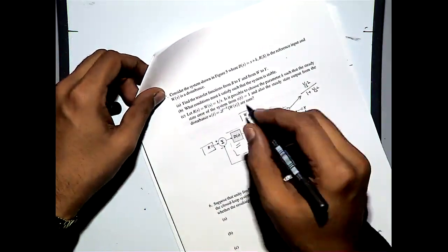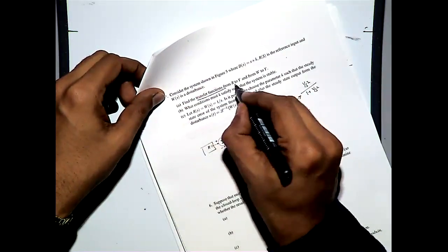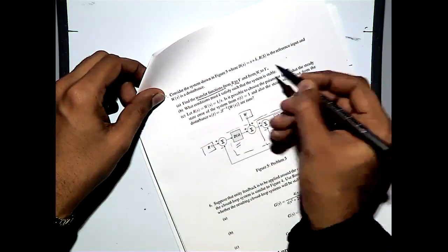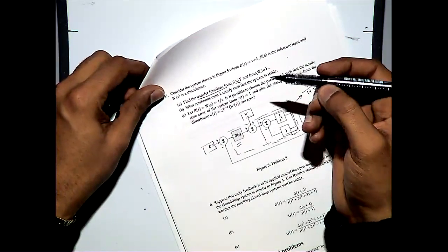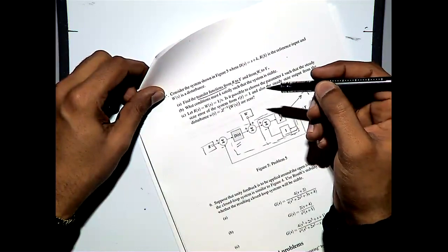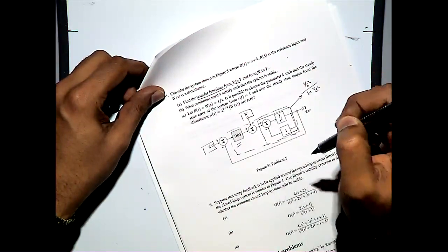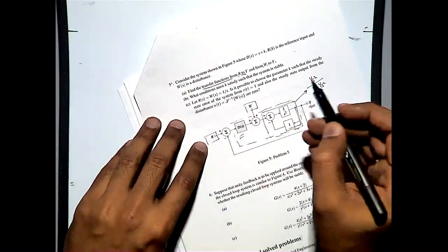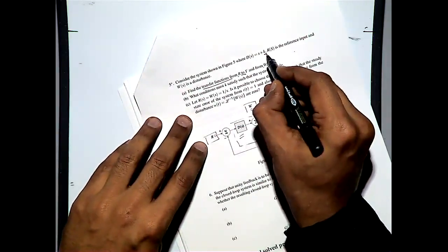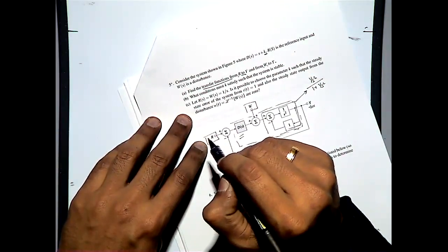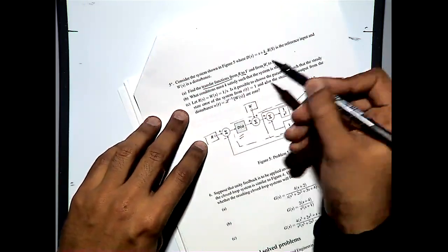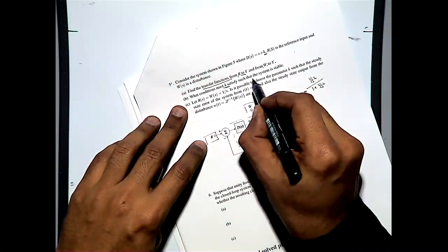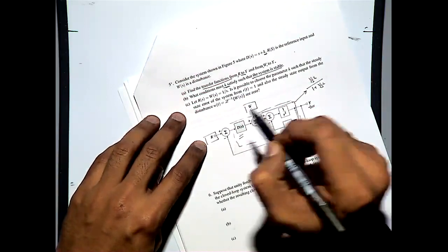Now you can actually apply the algebraic equation that we have covered today. So from that one you can find out the transfer function models from r to y and w to y, which turns out to be the sensitivity transfer functions of this system. Now, because in this case you have a constant k, you have to look at for what values of k the system satisfies the stability condition.